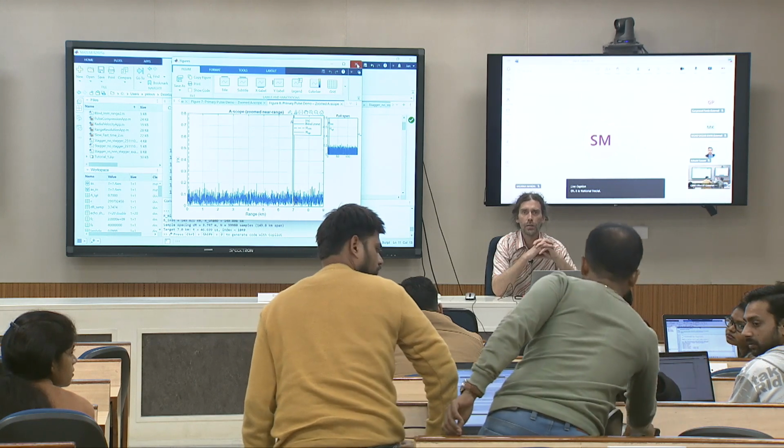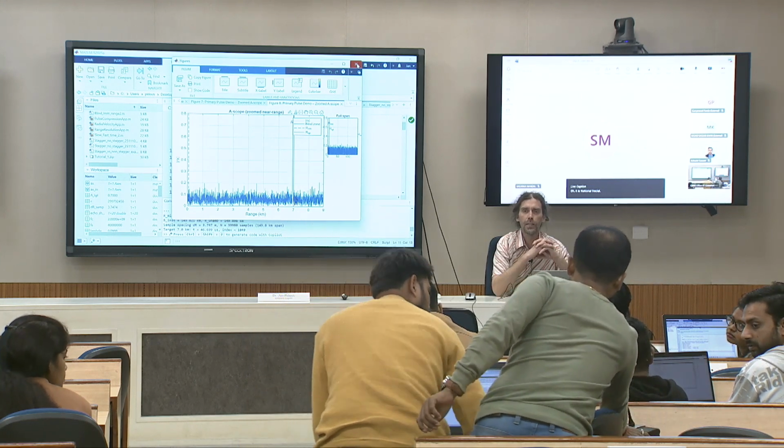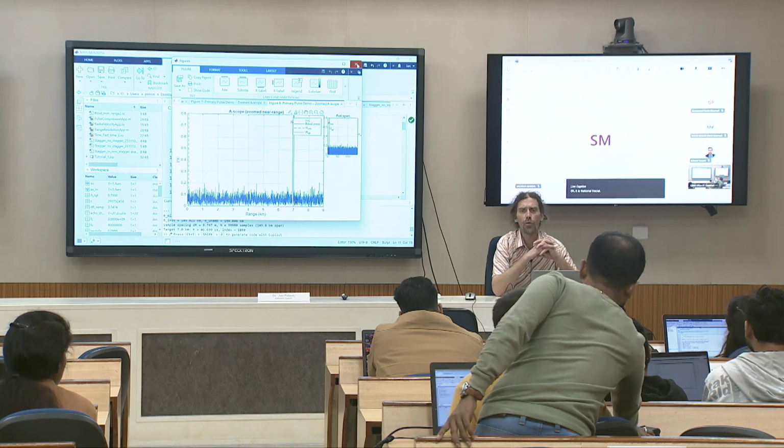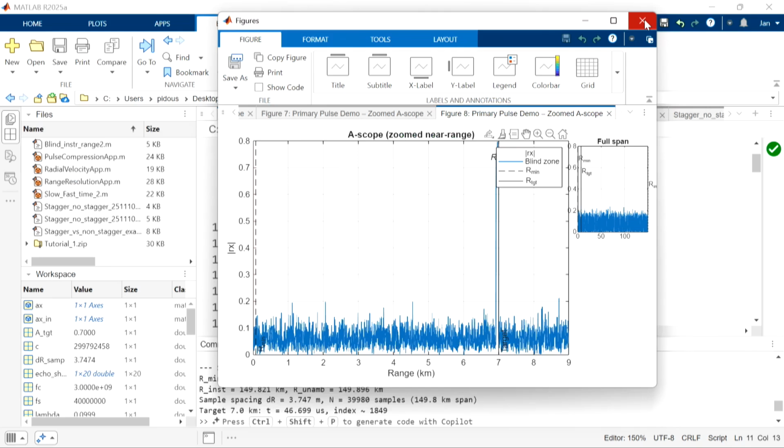Usually we like a little oversampling, 2 times, 3 times, 4 times, because if I want to process, I can always do decimation if I don't need it. But why do we use higher sampling frequency? Because in case I need it and I don't have it, I need to make the measurement again. And I don't want to go to a measurement if it's 150 kilometers far away from me.